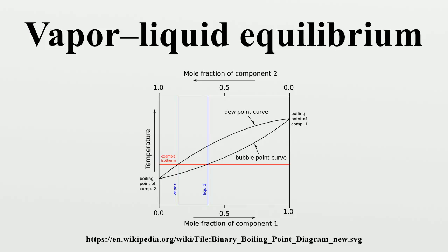Vapor-liquid equilibrium diagrams. For each component in a binary mixture, one could make a vapor-liquid equilibrium diagram. Such a diagram would graph liquid mole fraction on a horizontal axis and vapor mole fraction on a vertical axis. In such VLE diagrams, liquid mole fractions for components 1 and 2 can be represented as x1 and x2 respectively, and vapor mole fractions of the corresponding components are commonly represented as y1 and y2. Similarly, for binary mixtures in these VLE diagrams, x1 plus x2 equals 1 and y1 plus y2 equals 1. Such VLE diagrams are square with a diagonal line running from corner to corner for reference.